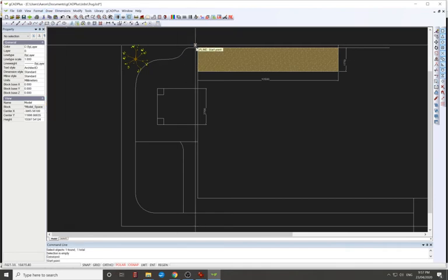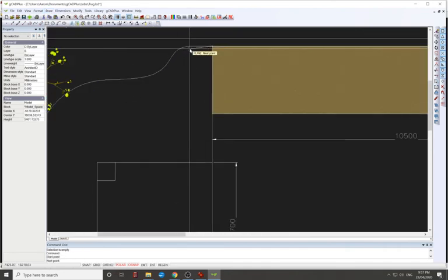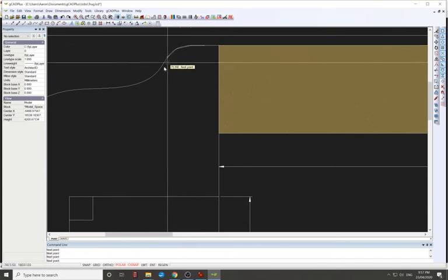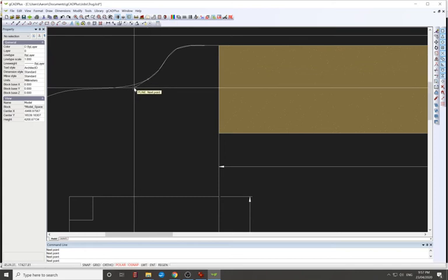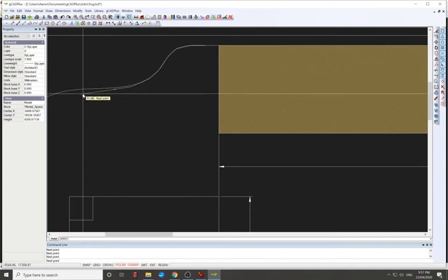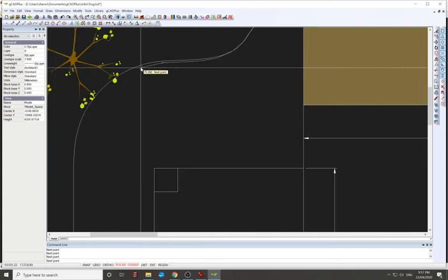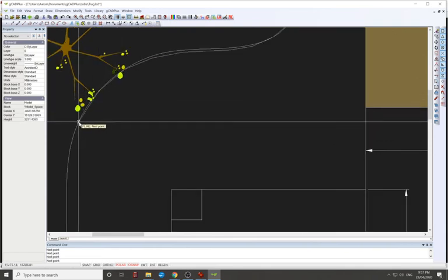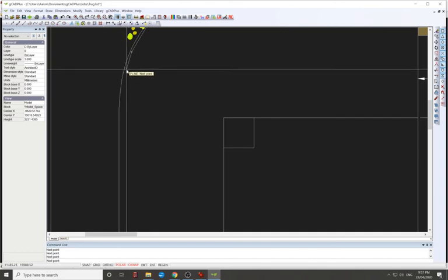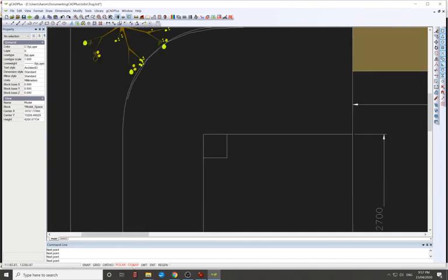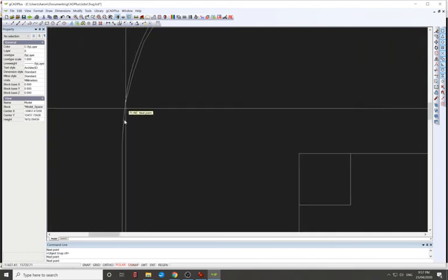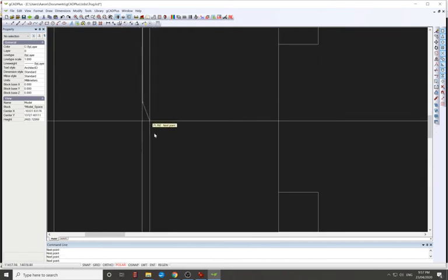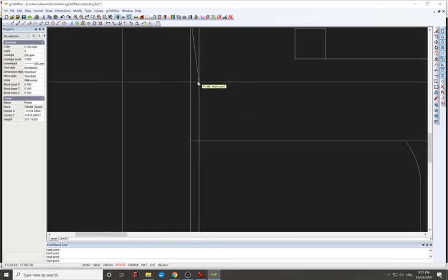Let's get this polyline in. So in this case here, you don't have to be too accurate. Just follow that polyline around roughly. This is just for the hatch. In fact, if you take object snap off, it's actually easier because you can pretty much just go wherever you want. Because if the object snap is on, it tends to want to snap to lines and trees and stuff.